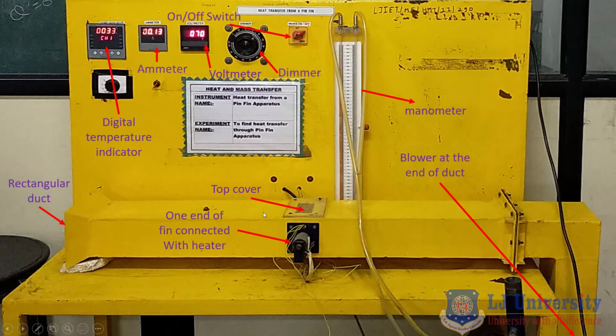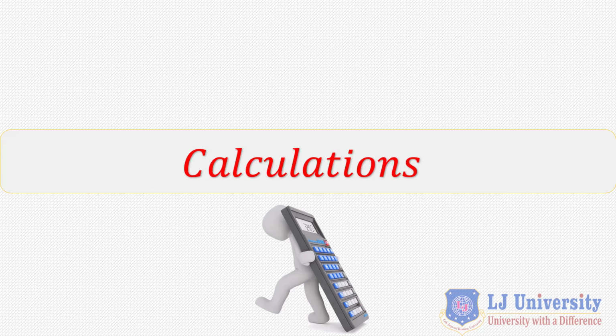If you want to do it by the forced convection method, then you have to switch on the blower, which is just below the ammeter. You can see there's one toggle switch over there. If you switch on the blower, the blower will start and the air will be forcefully passed through the duct. That will become forced convection. But right now we have done this practical by the natural convection method. In natural convection, no blower and no manometer is involved. You just have to open the top cover and take all the readings. So this is how you can do this practical.